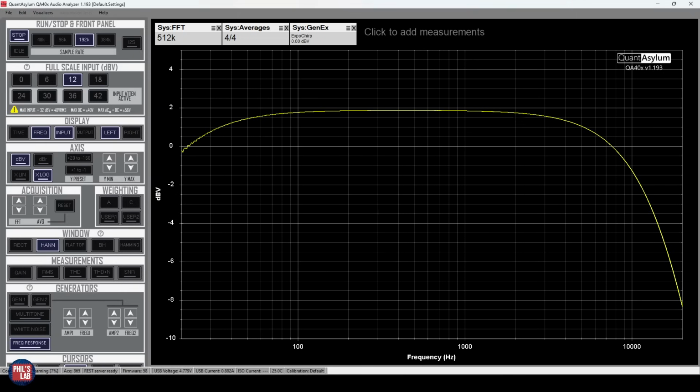We have a relatively flat passband, and we do actually have some passband gain of about 2 dB. So it's not at 0 dB, which would effectively just be a 1 times gain. But from this, we can see we have a fairly flat passband. Keep in mind the scale divisions on the y-axis on the left-hand side. So only down 1 dB at about 20-25 Hertz on the left-hand side, and only down about 1 dB, maybe around 5 kilohertz-ish.